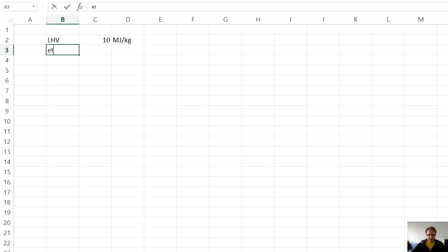The boiler will have a specified efficiency, given by a single constant value of 0.85. For the cycle itself, we will have a specified turbine inlet temperature of 535 degrees C and a specified turbine inlet pressure of 9 megapascals.